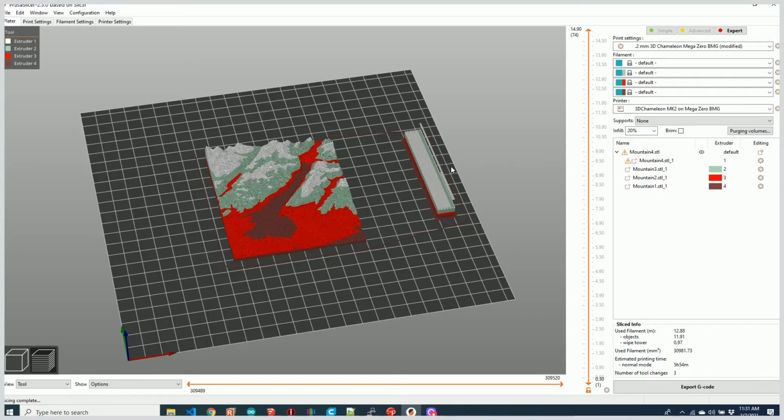And the idea here is that when you're loading filament, a little bit might dribble out. You want the nozzle to sit over here on the side so that if it does dribble out, when it moves back to continue printing, it's going to move on this side of the purge block, and the purge block is going to wipe that off. That way there's no dribbles or stuff between the part and the purge block. So always place your purge block between your part and your button, wherever your button happens to be placed.